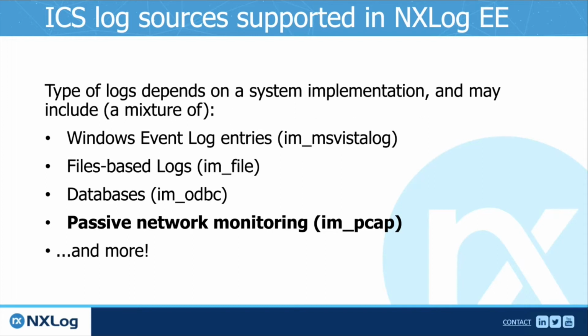So a lot of software generates different files, like debug files, like changelogs, like even status files, and this might be a very useful source of information. Some ICS systems use database engines to store their information, and here we can not only control the health status of the database itself, but what is probably most important, we can directly grab the ICS generated logs from the databases and push them forward to any monitoring tool.